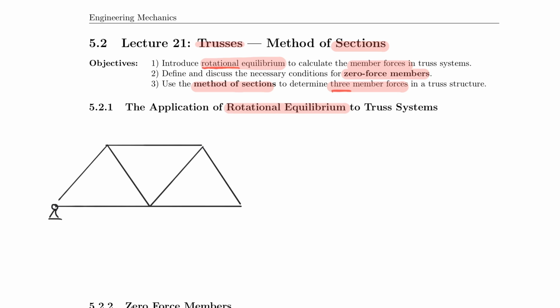So here I have a system that is simply supported, and I should just give it nodes A, B, C, D, and E. Also, remember that these are all technically hinges, although we usually don't show them anymore. A very common question now would be, please find the internal forces in, let's say, ED,